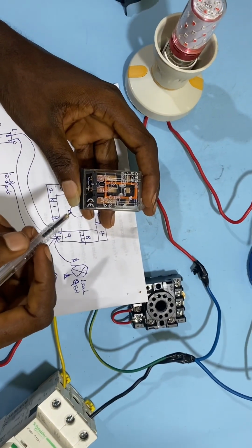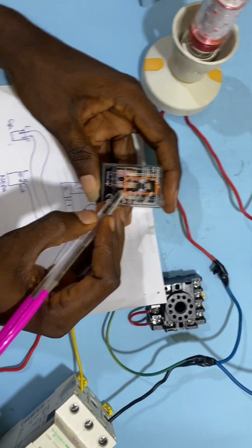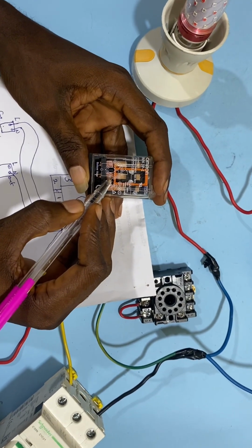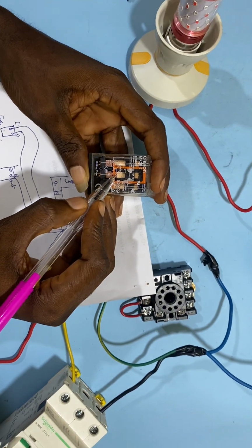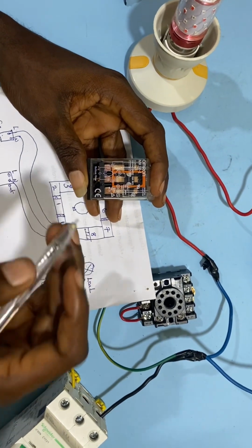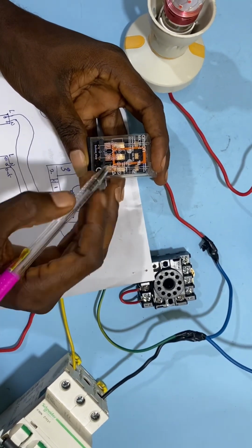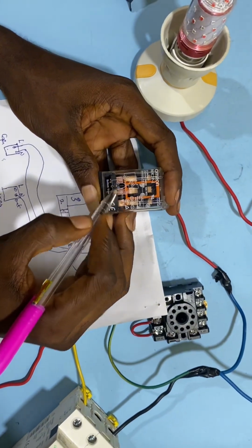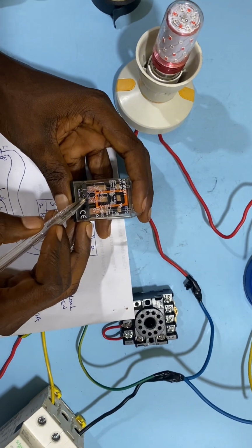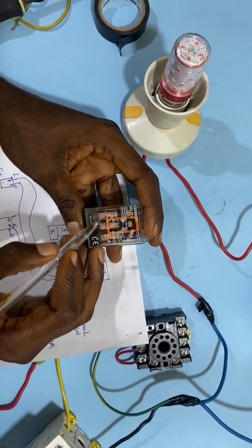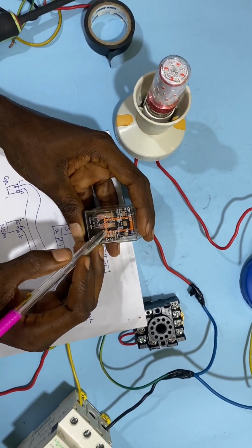We notice that pin 9 is normally open to pin 11 and pin 8 is normally closed. So how the operation is going to be done is that the coil contact of the relay is 2 and 1. So when we loop from 2 to 11, we are going to power this common, and the normally open will turn normally closed, and the normally closed will turn normally open.